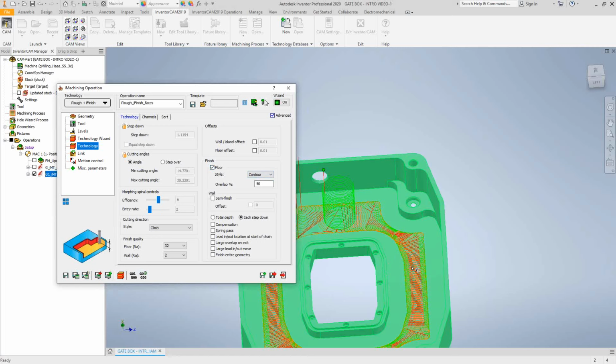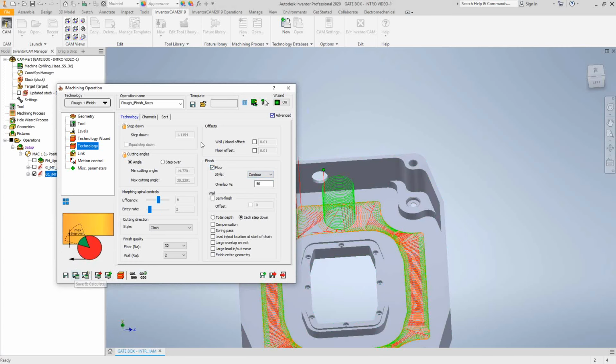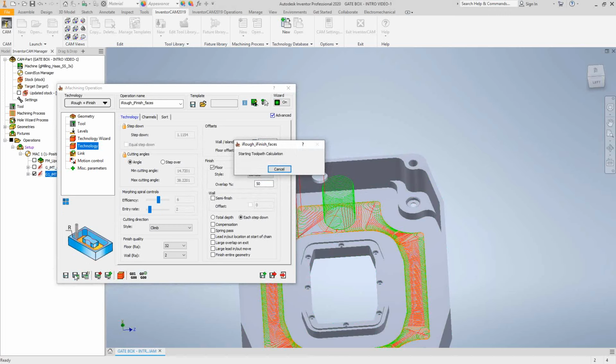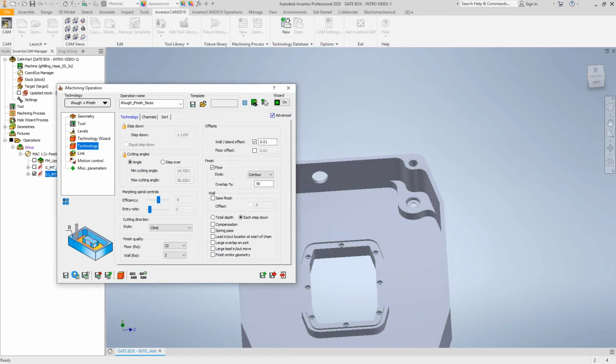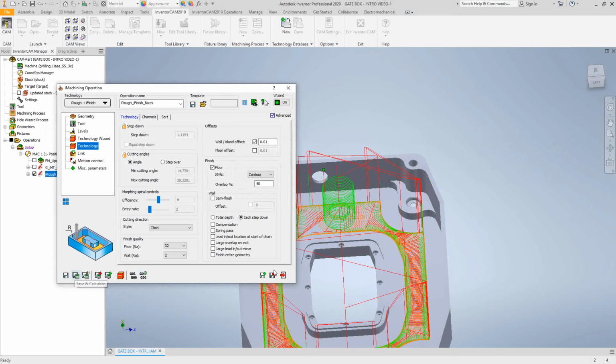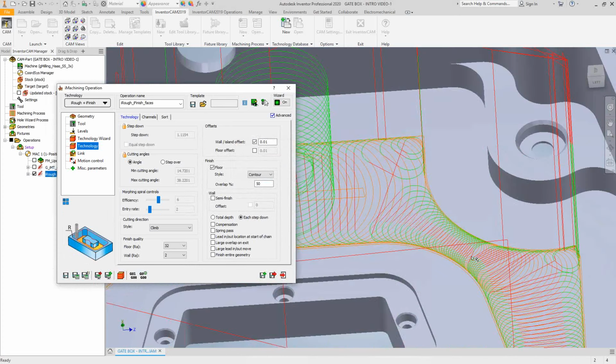It's going to be accurate dimensionally. It'll remove all the material, and it's still iMachining, so it controls everything. But those arc movements there probably don't leave a good finish. So what we could do is leave 10 thou behind, and then we can do an iFinish to clean up the floor. And because we're using contour style, it will leave a contour style similar to what you would have seen with a pocketing toolpath. And you can kind of see that if we zoom in.